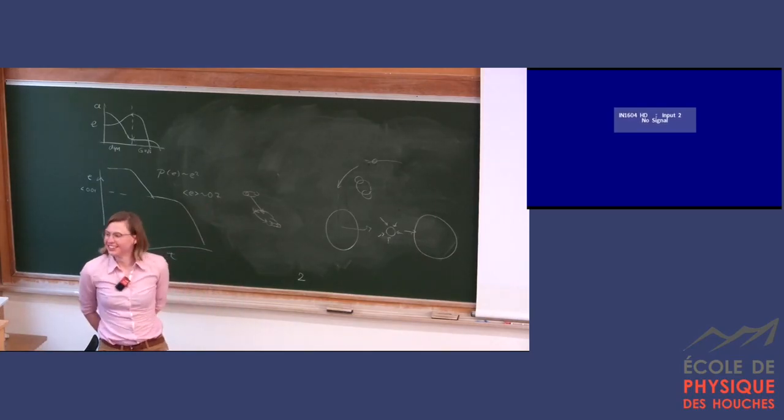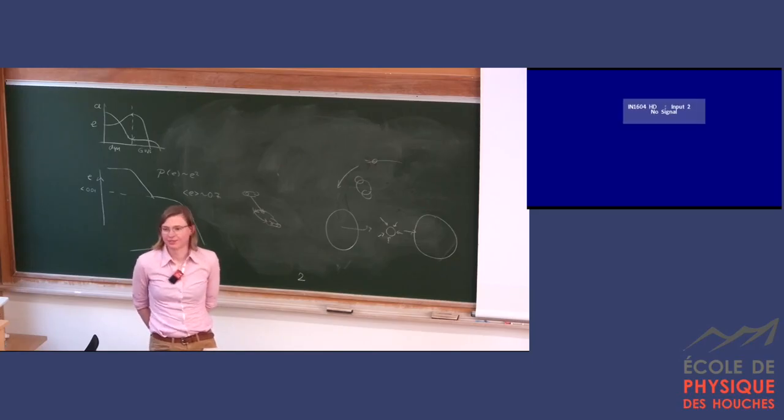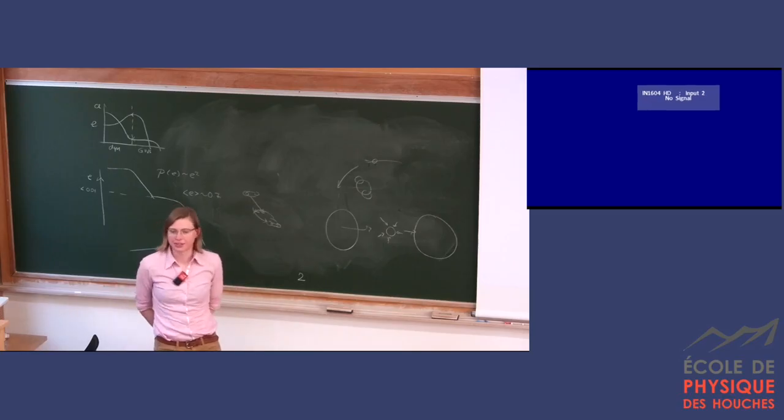Yeah. DWS is the differential wavefront sensing. That's where you measure the angular, yes, in the beams with the quadrants. Yeah, so you have 2, one per telescope, and with that you can measure the attitude of the spacecraft. If a micrometeorite hits, the spacecraft knows that it was tilted, and that gets corrected back. Of course, if you do it too quickly, then you lose constellation locking, and then we have to restart everything and start the process of constellation acquisition.